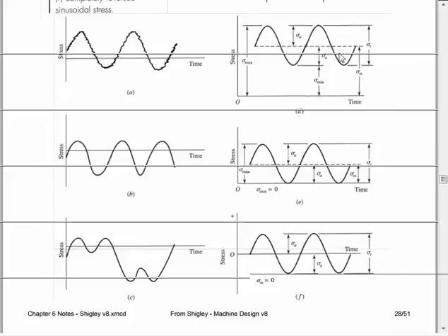And then the more general kind of loading would be a high stress, a low stress, a high stress, a low stress. And what we said was we can characterize this kind of stress loading by a mean value of the stress, the symmetric axis of the sine curve. So a mean value of the stress as measured from zero, and an amplitude value of the stress. And we have to be careful with our definition here because amplitude is not peak to peak. Our amplitude is peak to mid. Okay, and so half of the peak to peak loading would give us our amplitude.